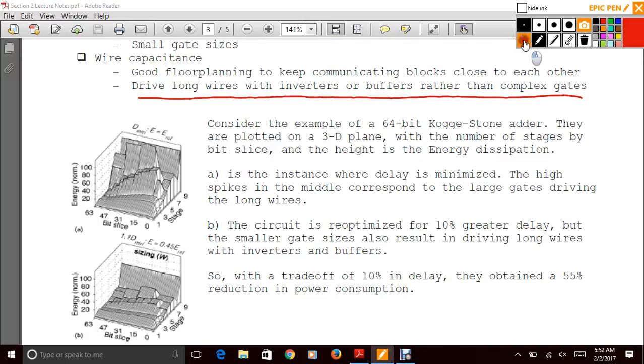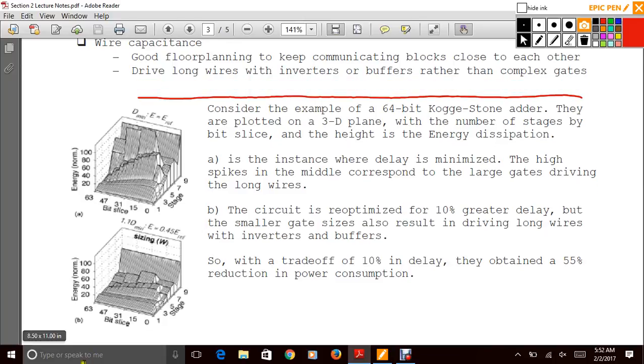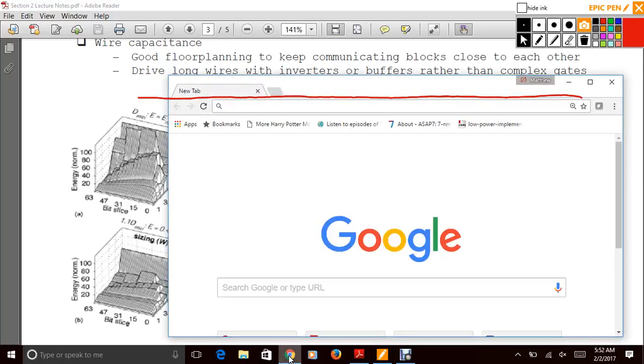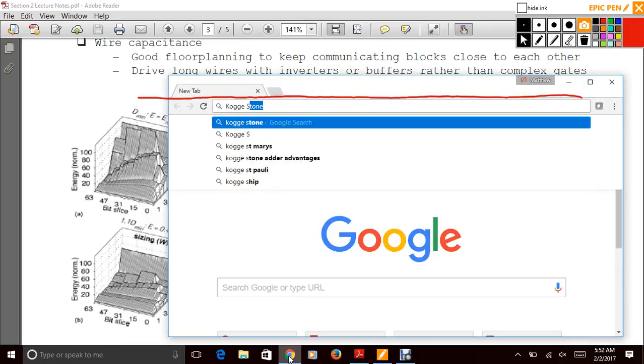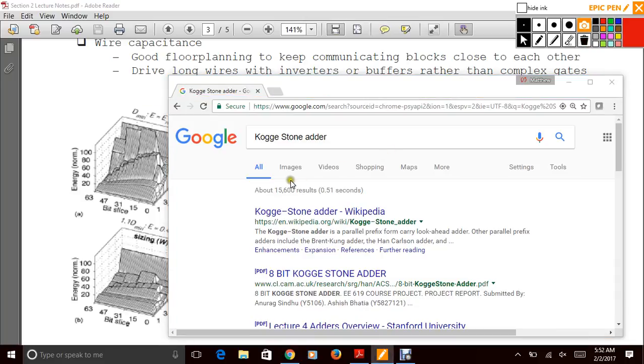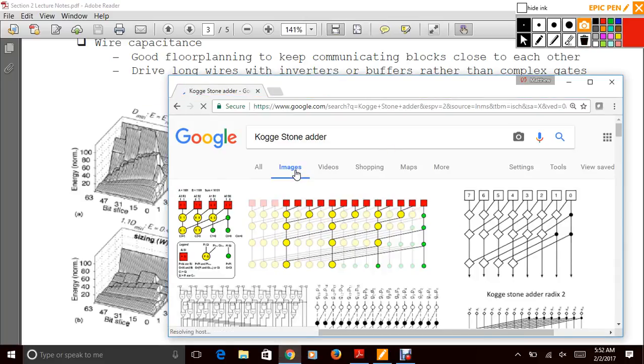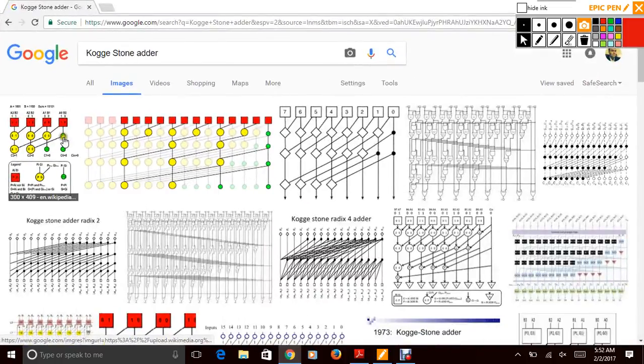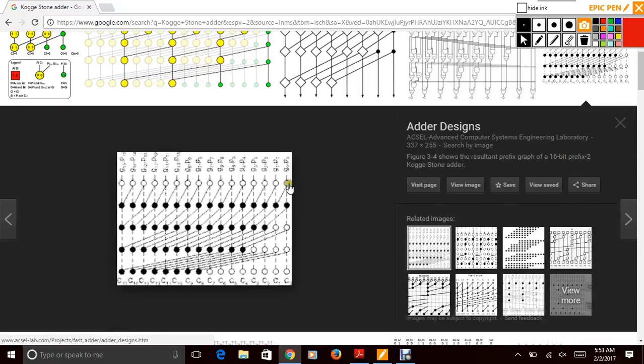And so something I wanted to bring up here, I kind of assume that you all know what Kogge-Stone is. So you all are familiar with fundamental adders. If you haven't, I can just go to images. What ends up happening is you have these propagate and generate logic at these different levels. The key thing for this particular lecture, and any of these will do, is you can see how you have these really long wires, right? And you're trying to do 8-bit. If you're trying to do 64-bit, these wires are going to go on for a long time.